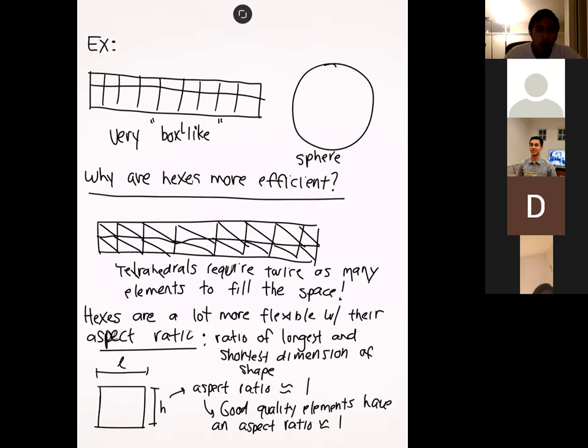Practically speaking, it's impossible to get a mesh with aspect ratio 1 all the way around, because you have to fit the elements into certain corners. But typically, a good meshing program will make it so that most of your elements are around this quality, because otherwise, if you have poor aspect ratios, that leads to some numerical difficulties.